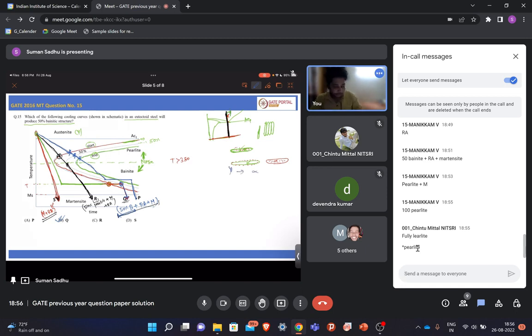So now only the different fraction of alpha or cementite may change depending on the temperature, right? Once the 100% transformation has occurred, as you are decreasing the temperature or quenching, the fraction of cementite and alpha may change, but the total percentage of pearlite will be 100%. So if you follow the P cooling curve, you will get a 100% pearlitic structure.